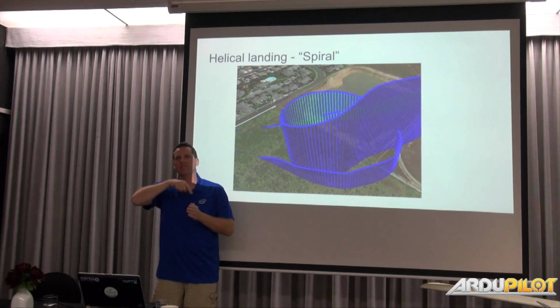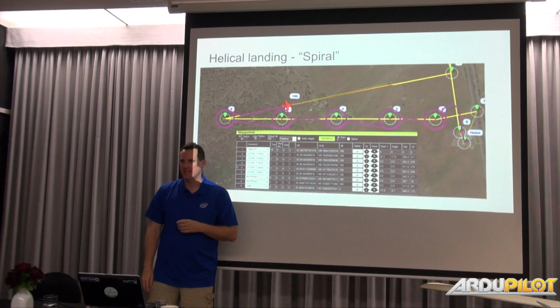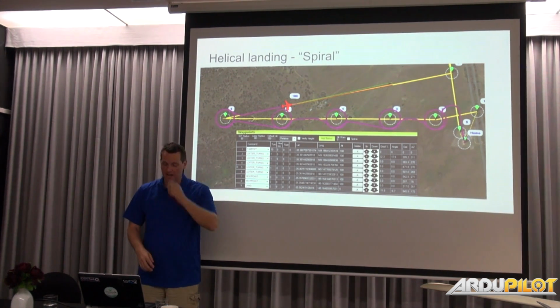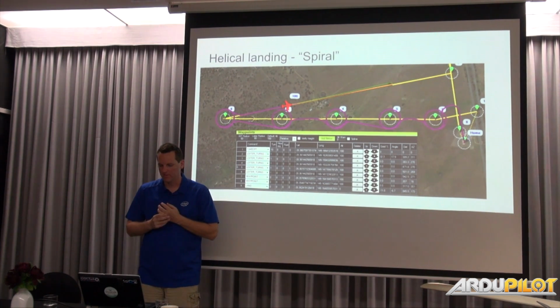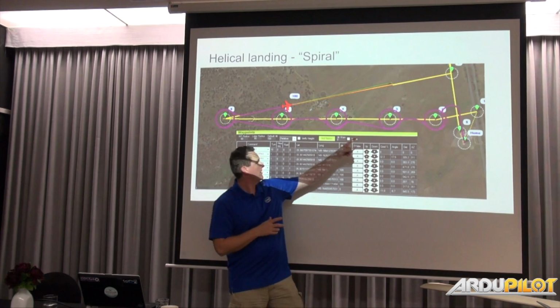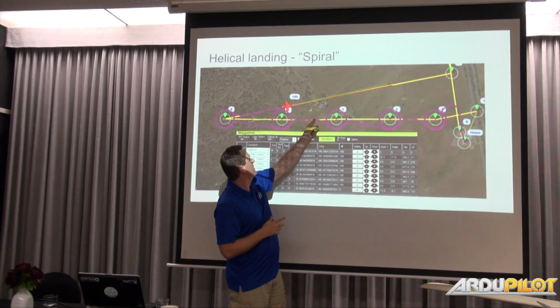It's doing a tangent exit. So tangent exit is something relatively new. This is a map showing a mission of what a tangent exit versus a regular exit looks like. So it's all about cross-tracking after you leave the point. So you'll see example point 3 here. You are exiting the mission on the tangent, versus 4, you're cross-tracking back to the middle.